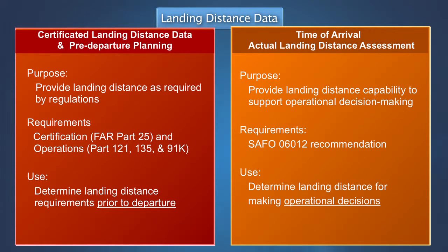It is especially important for flight crews to understand that the landing distance data established during certification and published in the AFM is not representative of everyday operational practices and does not reflect operational landing distances. This is true even when the AFM or QRH labels such data as actual landing distance, as shown in our previous example. This is because not all operational factors affecting landing distance are required to be accounted for by certification regulations.